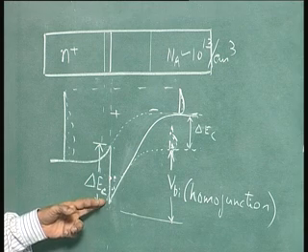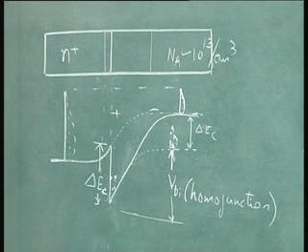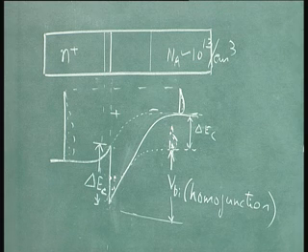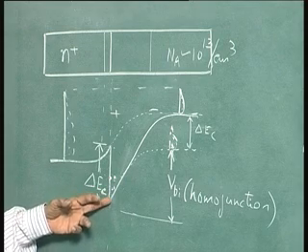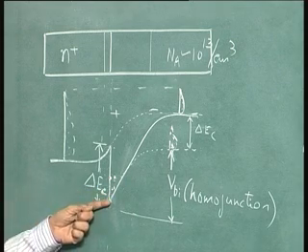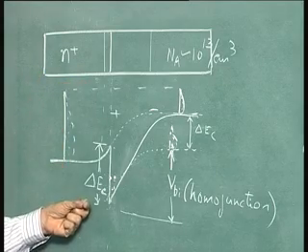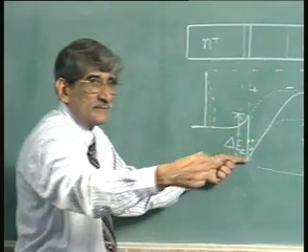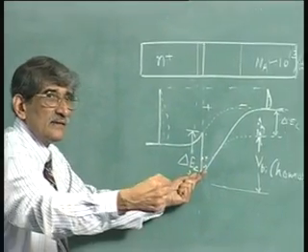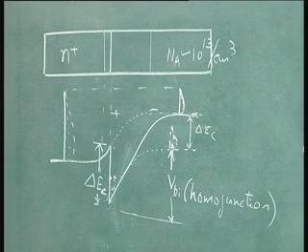Now, it is not enough if you have locked the electrons there, you must be able to use them. Now, use in keeping electrons which are locked up somewhere, you must be able to transport them. How do you transport them? Now, you have got electrons which have got high mobility, put a contact here and put a contact here. If this structure is going like this, put one contact between these 2 points. So, I apply voltage between the two, electrons will be transported like that. If I have source here, drain here, I can transport that. That is what is done here.